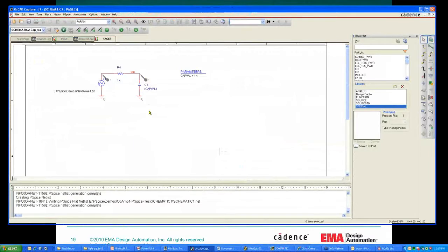I originally simulated this circuit using just a straightforward voltage source, and what that basically did was give me just the RC charging characteristic of that particular capacitor. And then what I did after that is I came in and, as I showed you before, I went to the results and selected the waveform and did a copy to clipboard, and then created a file from that waveform.